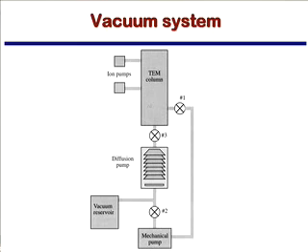Second, you'll turn on the diffusion pump, okay? And you will let that thing warm up so that the oil gets hot and it begins to work. That will take some period of time, and again, most microscopes will force you to wait the correct amount of time. During that time, you will usually open valve number 2 so that you do two things.